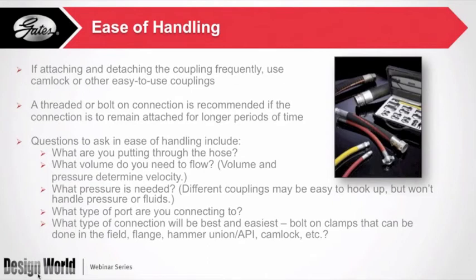And then the question to ask yourself every time that you select a hose or fitting for an application is, what is going to happen if this fails? If I pick the wrong fitting, what is going to be the issue if I have a failure? Is it going to be a spill, a hazmat leak? Is someone going to be injured? And then you're going to select based on the safety factor ultimately.